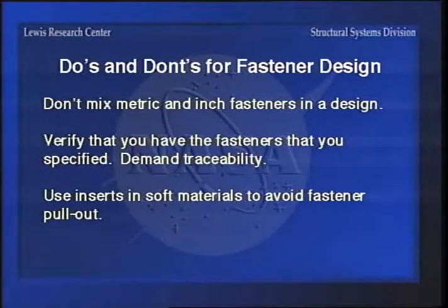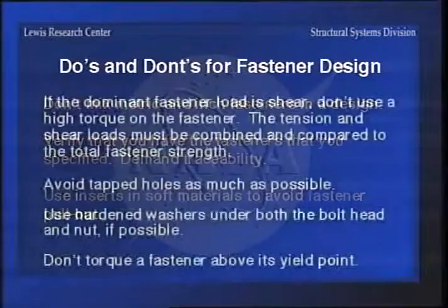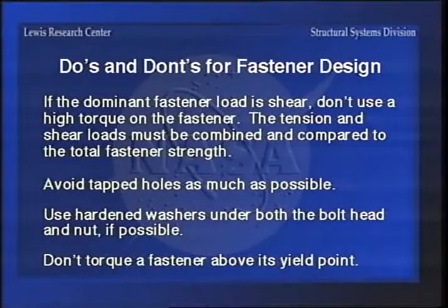Verify that you have the fasteners you specified, and demand traceability. If it is a critical design, make sure that you get the proper traceability of the fasteners. Use inserts in soft materials to avoid fastener pullout if you can't use through holes. If the dominant fastener load is shear, don't use a high torque on the fastener, because you have to combine the fastener and shear loads to the total strength of the material, so you don't want to use up all of it in tension if your primary load is shear.